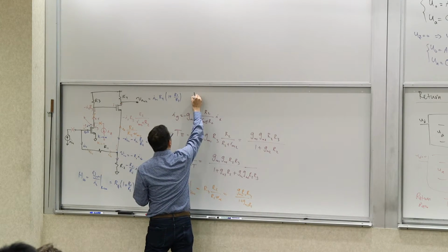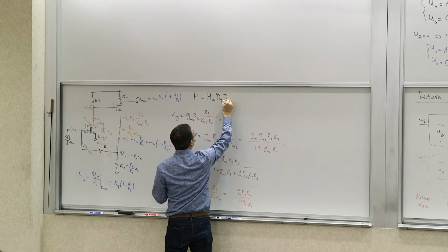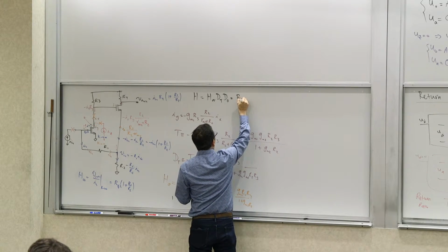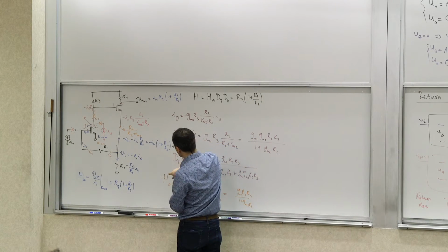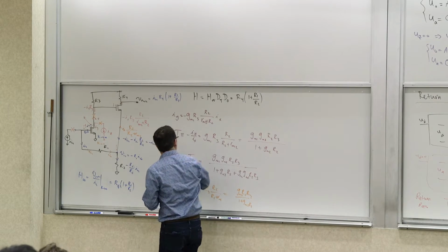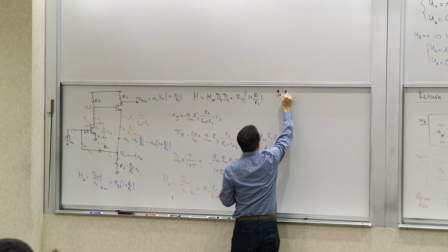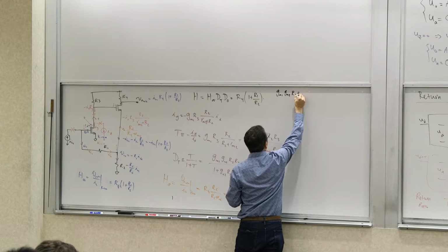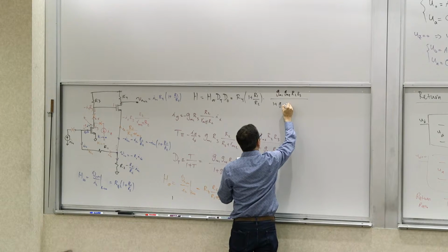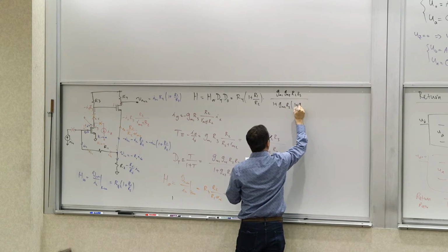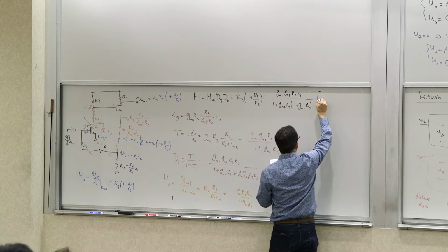So you can write H equals H infinity times DT times D0, which you can write as R4 times 1 plus R1 over R2, which is this part, the H infinity part down here, times this DT, which is GM1, GM2, R2, R3 divided by 1 plus GM2, R2, times 1 plus GM1, R3. And I am doing this for a reason.